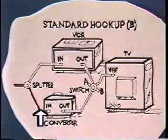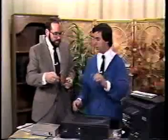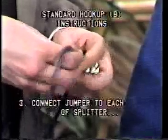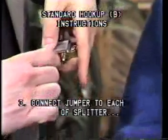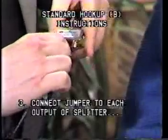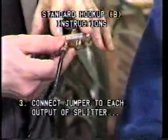Second thing we want to do, John, is take a jumper, and we want to hook the jumper up from one side of the splitter, from the output of the splitter, and we want to hook that up to the input terminal of the converter. Okay, once again, we're screwing the... Now we've gone one cable in, and this is one side of the output, so we're splitting the signal here.